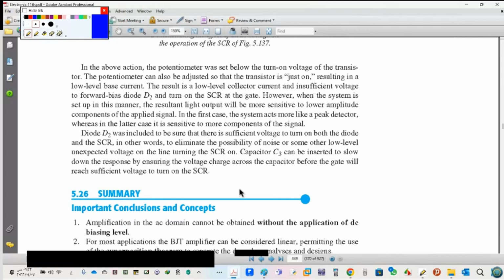Here we can see the effect of the capacitor. We see the C pi and C mu capacitors, and mostly both are given in the question if we have a model like this. In our study, I'm talking about myself, I start with the hybrid pi model because it's the general one. In our book here, we start with re because it's the easy one.